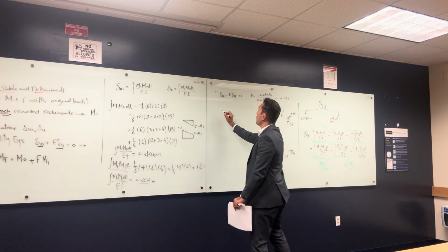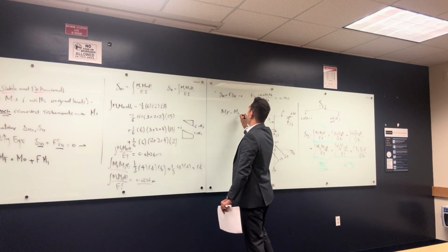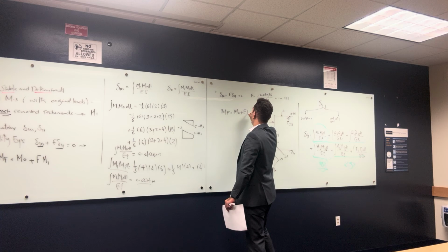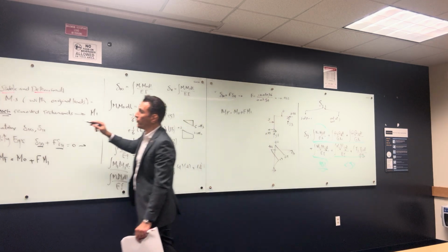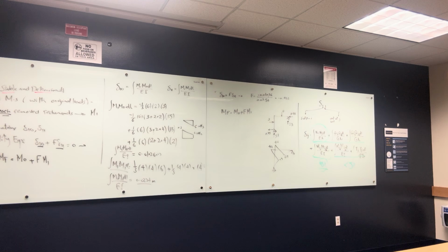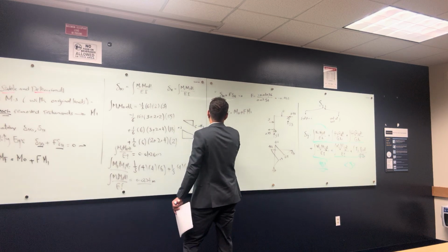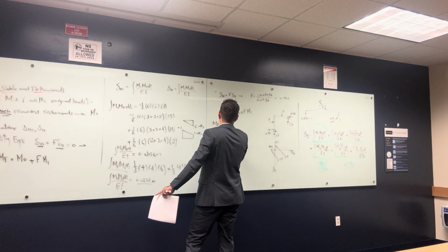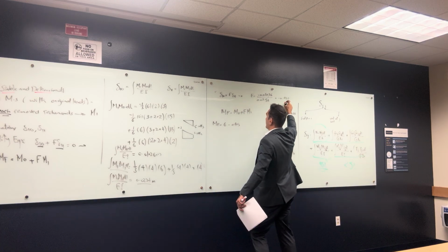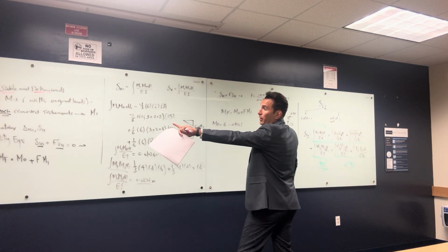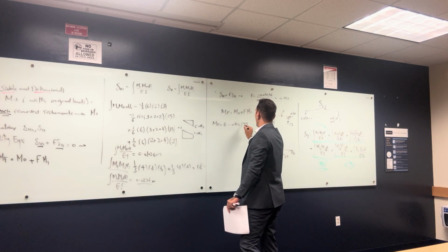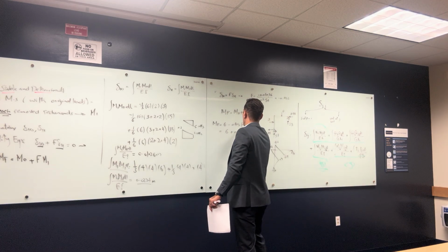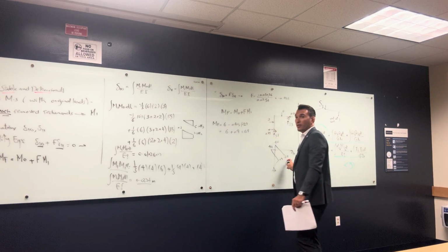And there's another way that I can do it. How? M final is equal to M0 plus F multiplied by M1. Get the value from this bending moment. This is 0, and 0 is going to give you 0. It's going to be 6 minus 0.45 multiplied by negative 2. Let's find out M1. MF is going to be 6 minus 0.45, which is the value of my reaction, multiplied by the negative moment that we got from M1, it's 2. So you'll find it's a negative, so it's going to be 6 plus 0.9, which is going to give you 6.9, which is the value here.